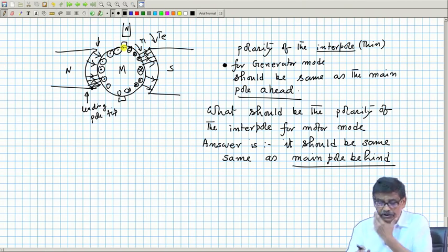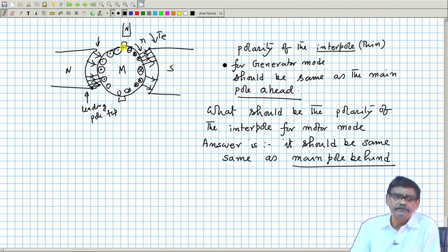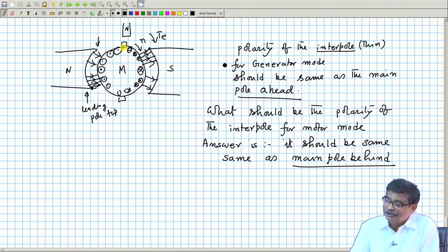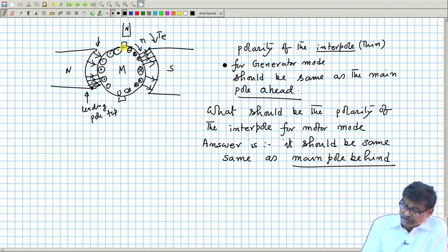In fact, with this last word I will stop. You will hear, for example, that an induction motor's rating could be in kilovolts. In synchronous machines also, motors of the order of kilovolts are available. Very large voltage synchronous and induction motors are available. A 6.6 kV induction motor in industry is very common. But in a DC machine, you will never hear a voltage rating of that level. The voltage rating of a DC machine may be at best 1000 volt, that is all.